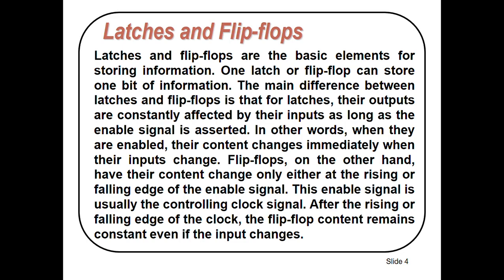So we should discuss the difference between latches and flip-flops. Latches and flip-flops are the basic elements for storing information. One latch or one flip-flop can store one bit of information. The main difference is that for latches, their outputs are constantly affected by their inputs as long as the enable signal is asserted. In other words, when they are enabled, their contents change immediately when their inputs change.